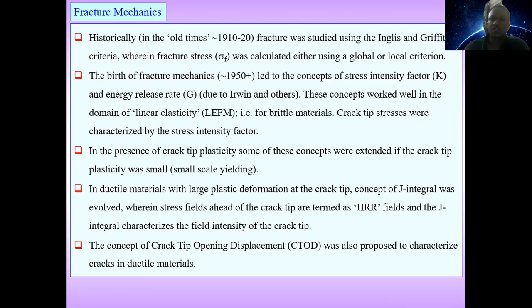This concept worked well in the domain of linear elastic fracture mechanics for brittle materials. Crack tip stresses were characterized by the stress intensity factor. In the presence of crack tip plasticity, some of these concepts were extended if the crack tip plasticity was small, or very small scale yielding.